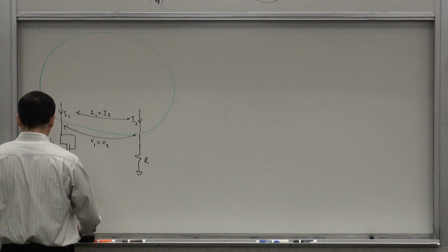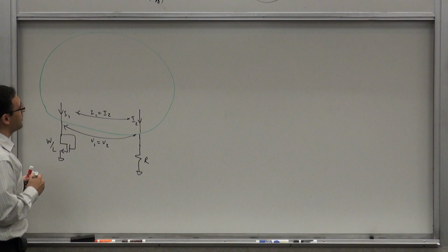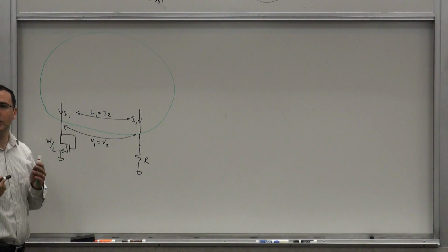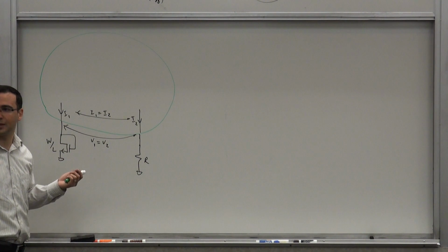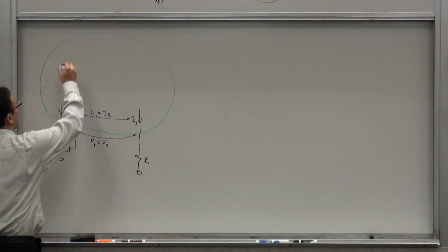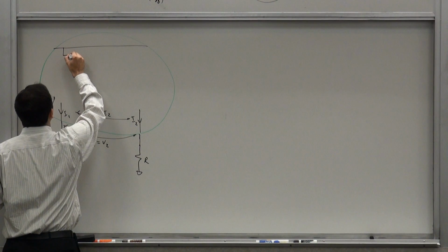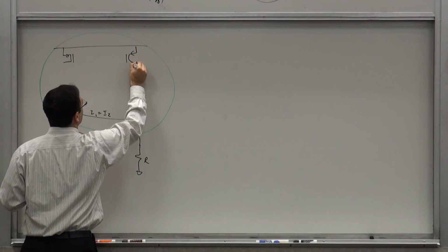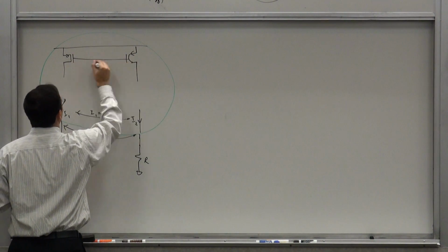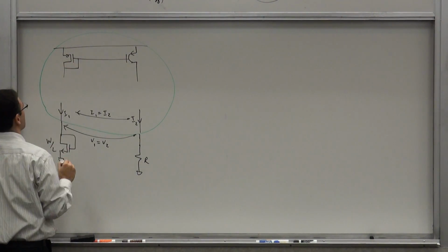So anyway, if I want to get, first let's do the currents. If I wanted to equate the current, make something that forces two currents to be equal, what is that? We know how to make that, right? It's a current mirror. So I'll start with the current mirror. Can make a PFET current mirror. Two branches, one side is diode connected to get this bias voltage.